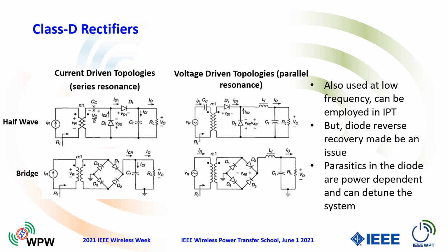One of the things that makes these circuits quite tricky, as they are shown here, to operate with IPT is the reverse recovery of the diode and the parasitic capacitance of the diode. So instead, we tend to try and use solutions that wrap capacitors around the diode as part of a resonant circuit, so that we are no longer suffering from the reverse recovery loss of the diode. We try and make this a resonant process rather than a hard switched, very fast recovery process of the diode.